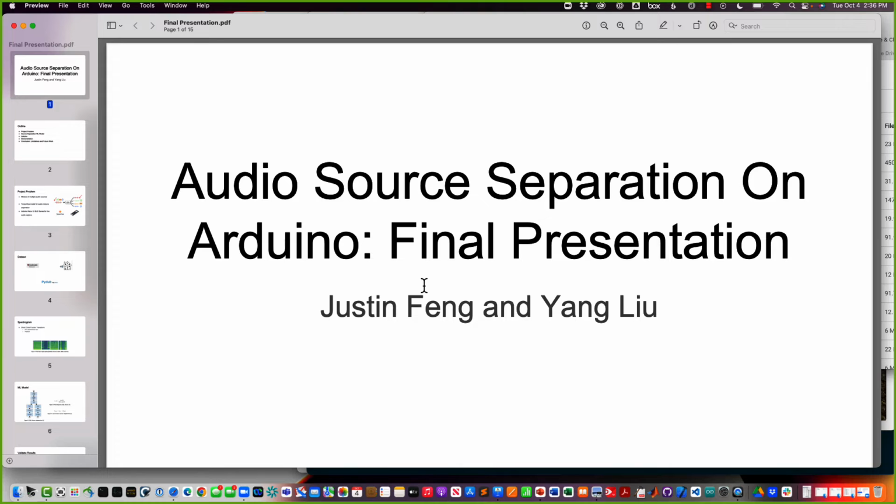If a sound source was somewhere in the back wall and right in the center line, then the two signals will arrive at the two microphones simultaneously, because they're equidistant. But if the source was in one far corner, it will arrive at the gray table later and the brown table first. And if these two were tightly synchronized and processed together, then we can begin to say which direction they are coming from. So if you have multiple microphones, you could figure out the direction.